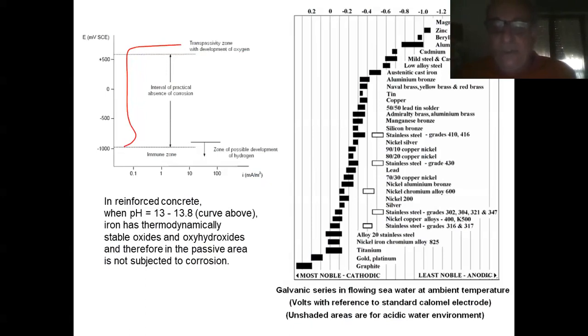Please also note that you have some white rectangles which represent instead the conditions in acidic water rather than seawater. There is a quite considerable difference. And you may easily consider that the higher you go, and so the lower the value of your potential, the more oxidized, the more passive your material gets.